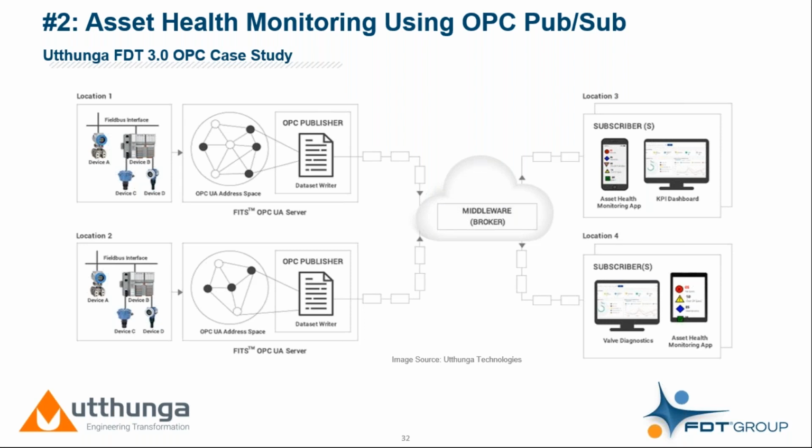As you know, with the client-server architecture, it is required for the client and the server to maintain sessions. When we have to maintain the session, it consumes resources. So when you have to scale this application, you will have a problem managing each session and connection and handling this data. With the OPC PubSub mechanism, the subscriber will not be aware of the publishers, and the publishers will not be aware of the subscriber.